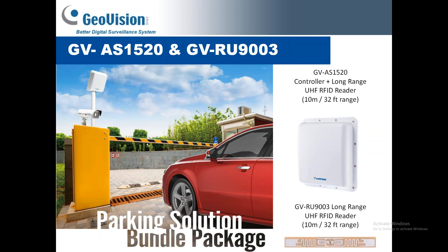Access control solutions for gates. We do offer some long-range reader options. The current model on the bottom right, the RU9003, is a long-range reader that has 32 feet of read range. It comes in a 64-bit or a 26-bit. The 26-bit would allow you to use it on pretty much anyone's access control panel. And then if you see on the bottom right is the sticker credential that would go on the windshield or the headlight of the vehicle.